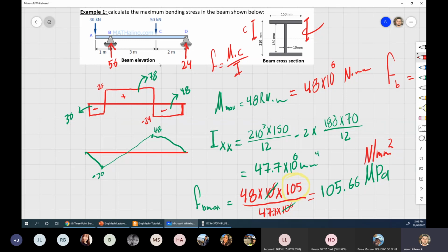So we now have the bigger picture, the complete picture. We have the loads. From the loads, we learned how to change these loads to a more graphical view, which is the bending moment diagram and shear force diagram. Now understanding the strength of material, we combine them together to calculate what we call stress. By knowing the stress, I can compare, do you remember that picture I showed you?